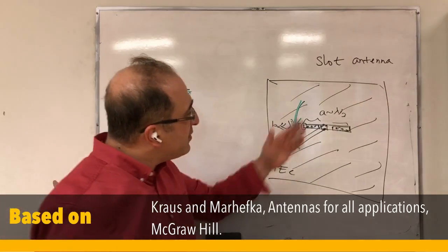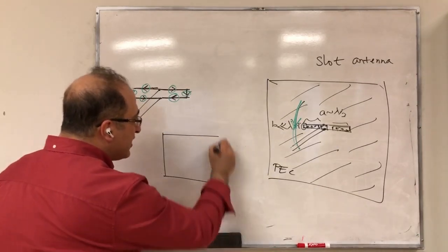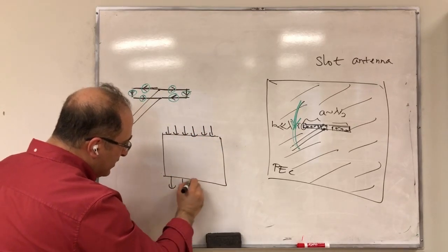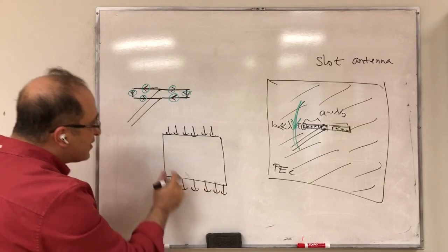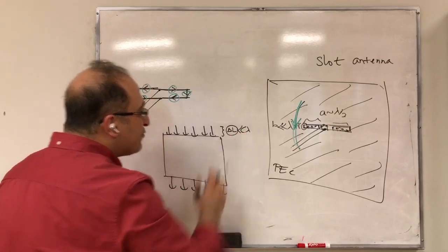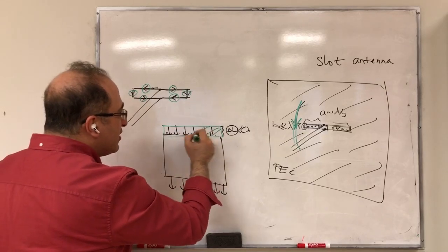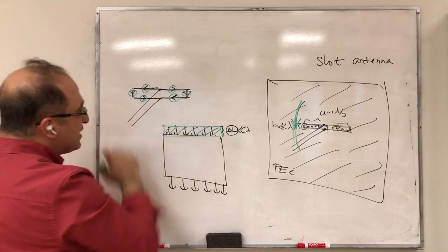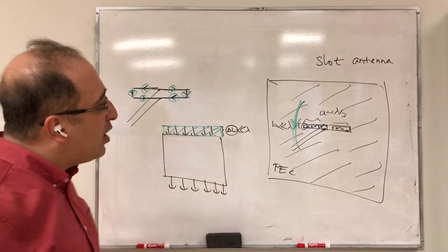Something that's also interesting in this antenna in terms of its application, remember in the case of the patch antenna, we thought of it as two radiating slots, although there was no PEC plane and a cut through PEC. But look at this structure. This width was delta L, which was much smaller than lambda. This was the fringing effect. So as you see, if you now think of this as your aperture, you can also think of this as radiating slots because this is small with respect to the wavelength. So this is something to keep in mind when you are looking at that.